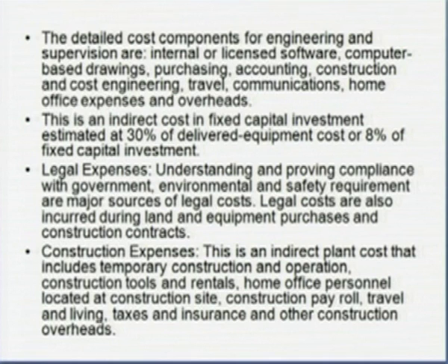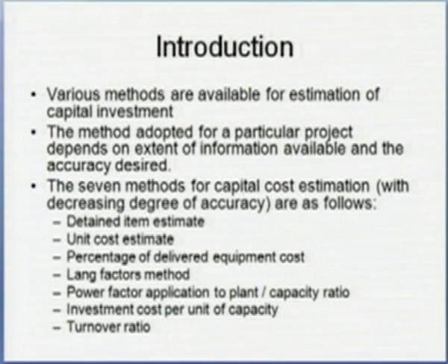Now, we go further to exact estimation of the project cost, or what methodology we need to adopt for estimating the fixed capital investment. The methods available for estimation of project investment can be listed as typically 7 methods: the detailed item estimate, the unit cost estimate, the percentage of delivered equipment cost, the Lang factor method, the power factor application to plant capacity ratio, investment cost per unit of capacity, and turnover ratio.